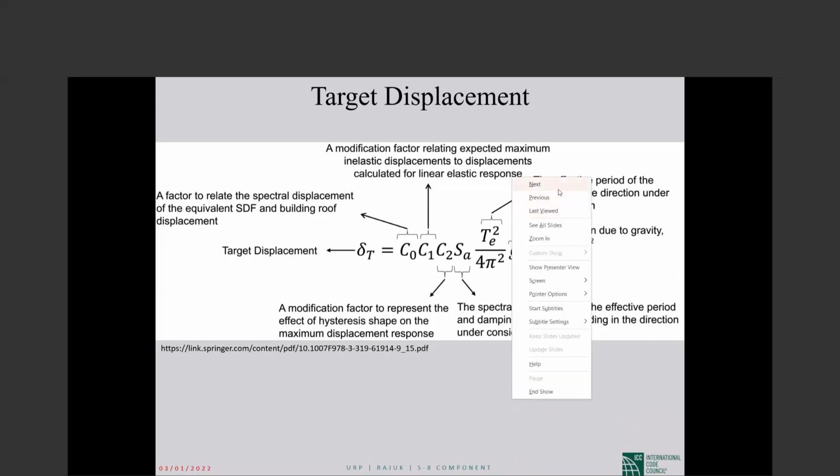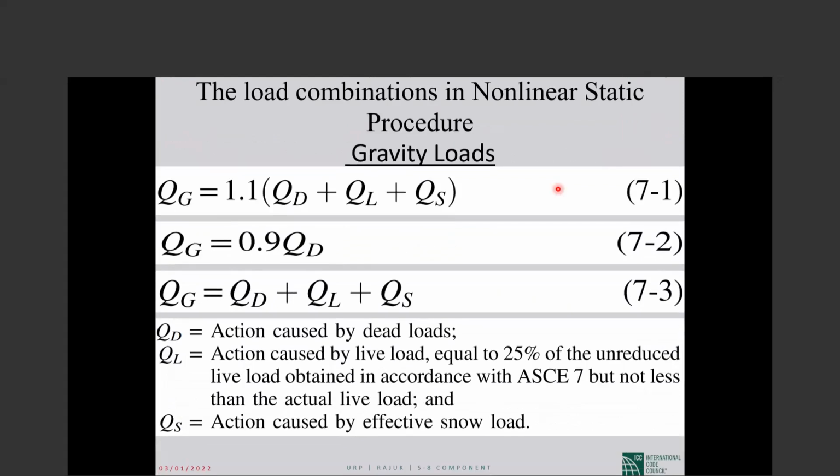Therefore, the gravity loads that we should put, because we are dealing with nonlinear analysis, superposition is not applicable. So first we should put the gravity load on the building, and when the gravity loads are there, we should do the push.